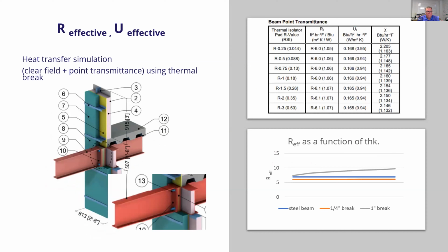What happens then if we use a material that's too thin? If we try and make a break that's too thin? Here again, if we look at the first column in the range of R values, even if we have a material that starts out with R3 and we only make it a 1/4 inch thick, its actual R value is 0.75.